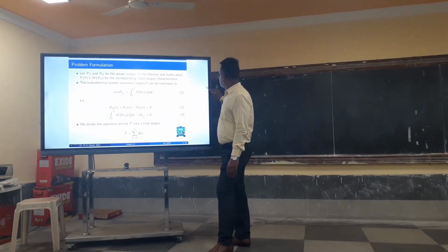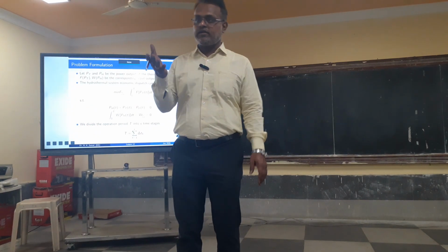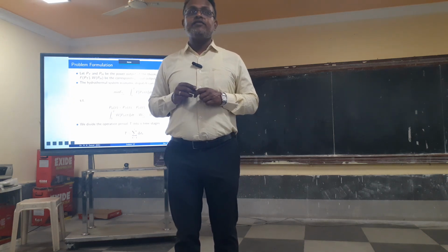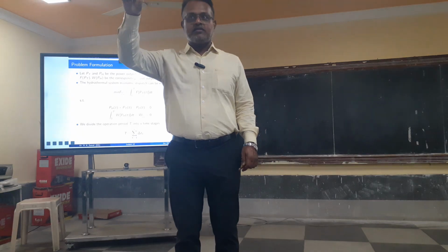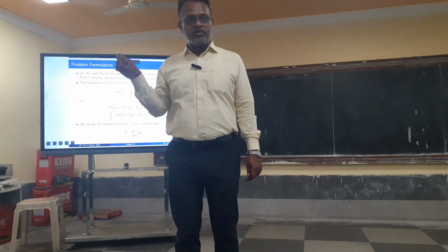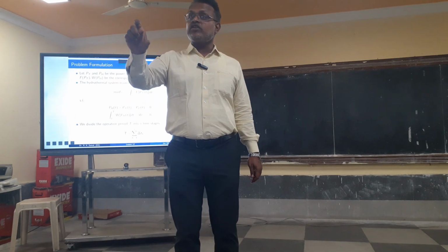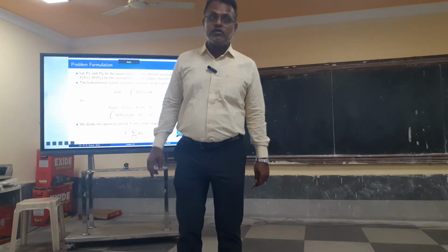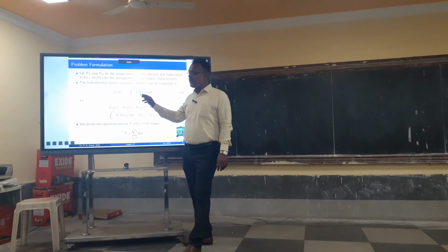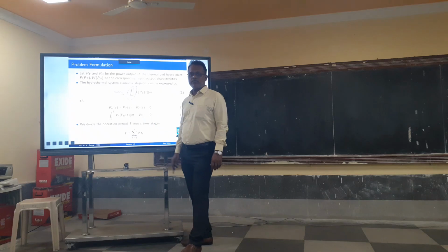So, from a long question perspective in your exam, you will be asked to formulate the problem. So what was the formulation? Minimize Ft, summation Fi, subject to power balance, summation of generation equals demand, and the inequality constraints. But here, the additional constraint is the total availability of the water. So here you will see there is an integration sign. Why? Because you have to find it for the whole time period.